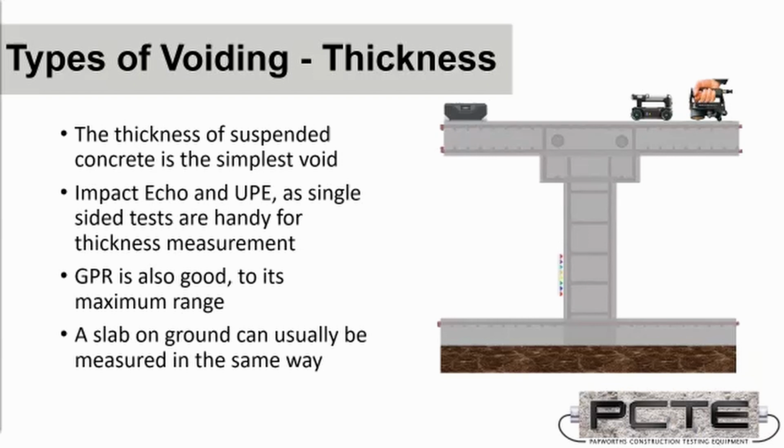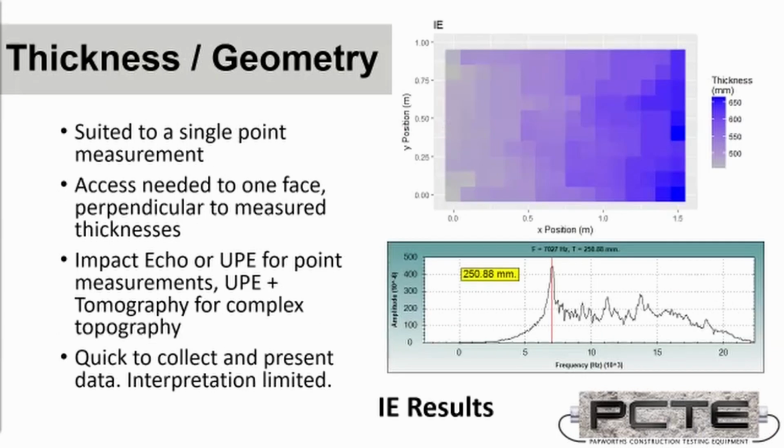And one defect that could be a thickness measurement to keep in mind is when you're looking at structures like waffle slabs or pod slabs, where there's polystyrene void formers forming thin slab areas, then thicker beam areas, which are poured in situ. These techniques could be appropriate to determine that the void formers have not moved or changed.